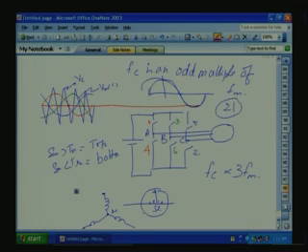This is one way of suppressing the effect of low order harmonics. Because the neutral is removed, the current harmonics at 3 times FC, that is the third harmonic, and sidebands will not be there. So, the next higher harmonics will be at 2 FC and its sidebands.